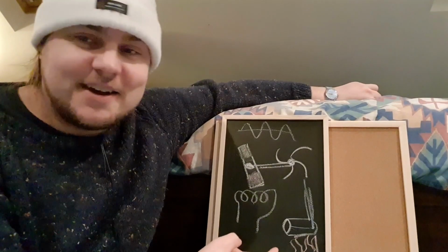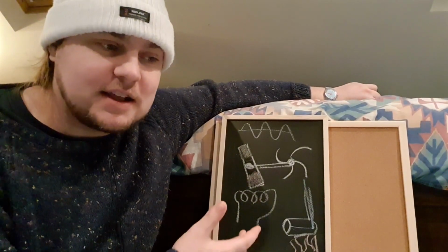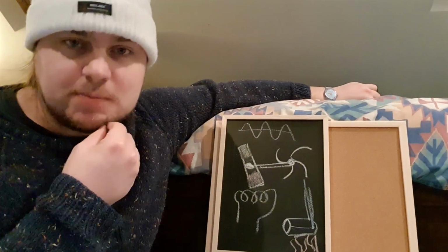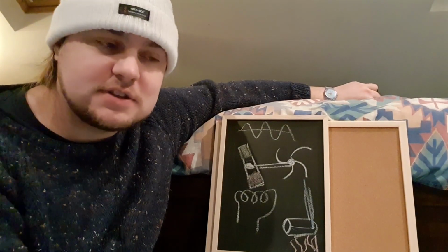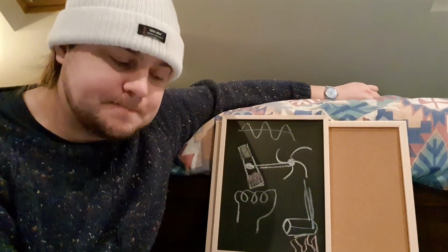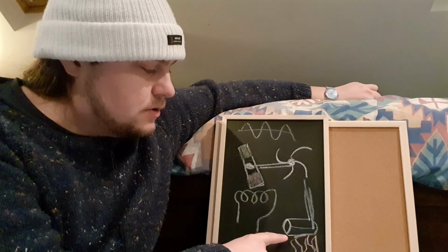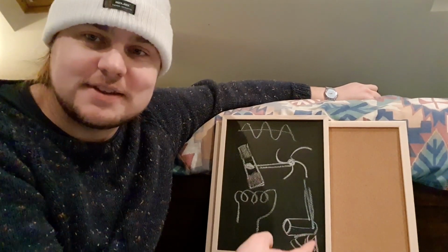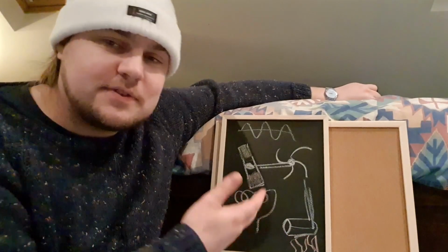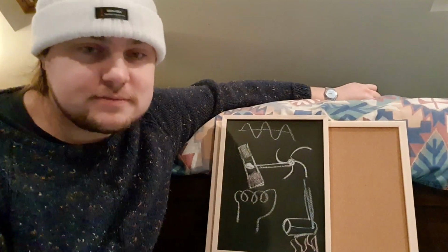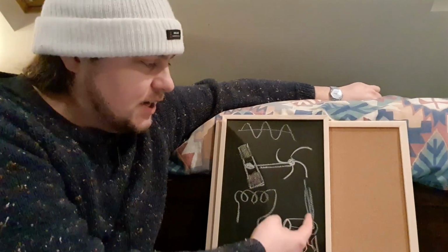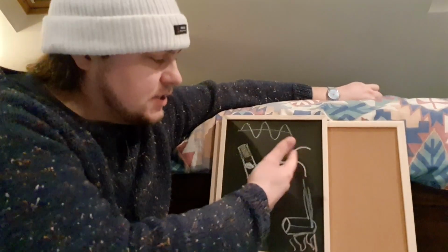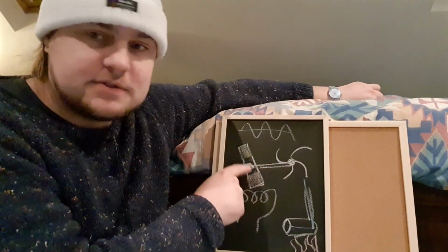So this is how we generate electricity. This is the classical way to generate electricity for a grid, and the national grid was mostly built around coal-fired power stations on the island of Great Britain. So this is a boiler. It's like a tank of water, and there's some sort of fire underneath the boiler. The fire's from coal or gas or oil. Water is heated, and it turns into steam, goes up, turns a turbine, which is like a water wheel for steam. The turbine is connected by a drive shaft to a generator.